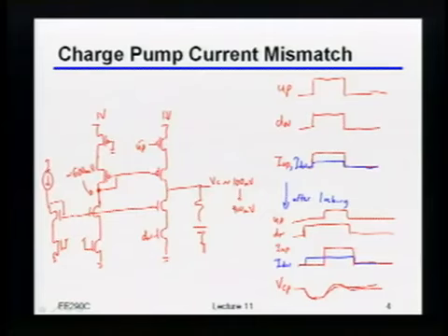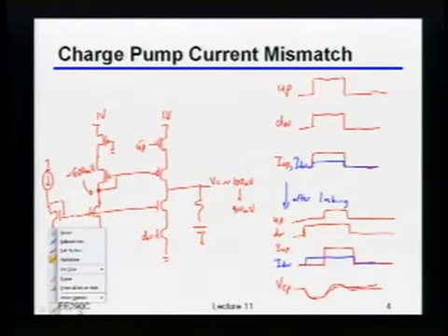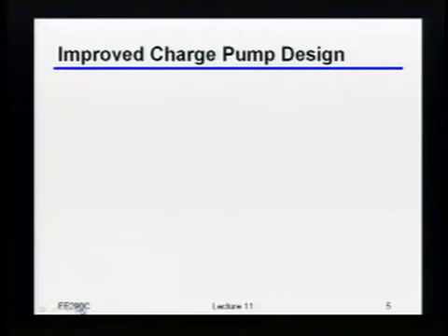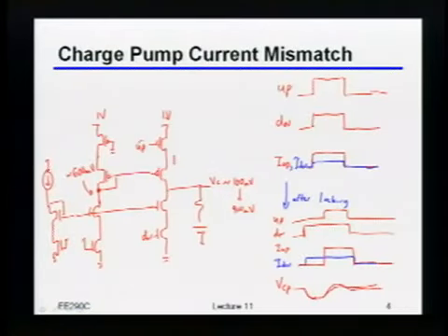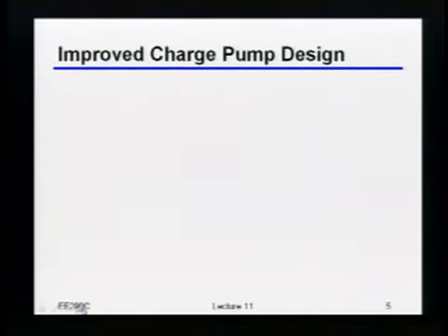Yeah, basically, right? Okay, and actually, you don't even have to be that direct. All you're really trying to do is build a better current mirror, right? If I want the best current mirror I can get, then all I have to do is make sure that whatever voltage I have over here, I also get that voltage over here, right? And then as long as the devices match, then I should indeed have a good current mirror, right? So let's just quickly sketch what that would look like, okay?